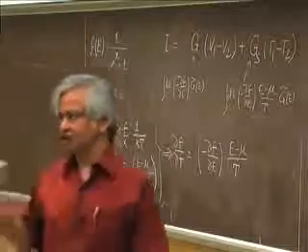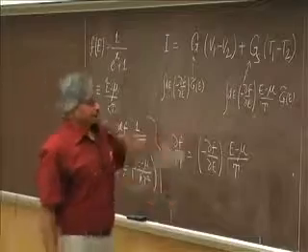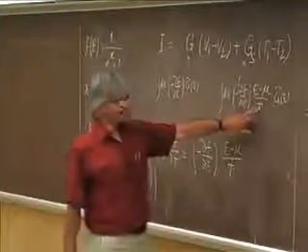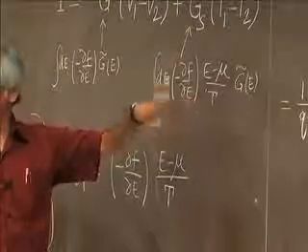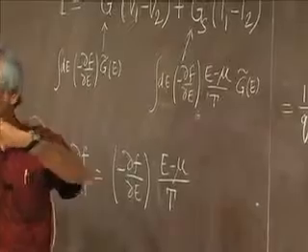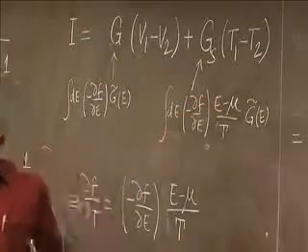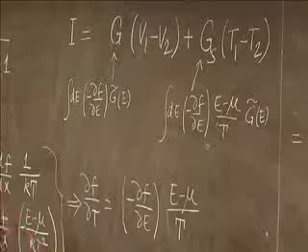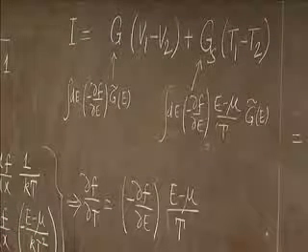But same with the mu1 and mu2. You could ask the same question, right? To some extent. So when you write a T here, it could be either T1 or T2. And the point is, it shouldn't make a difference because we are talking of small differences. So when you use these thermoelectric devices, the normal temperature difference is about 200 Kelvin or something like that.